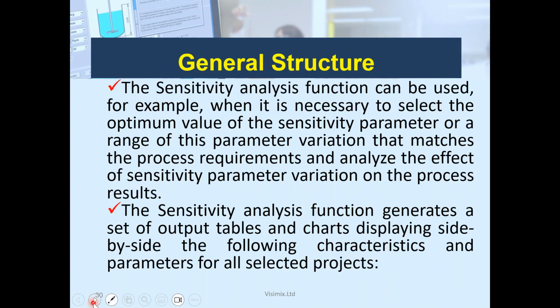So once we are doing all this range from the minimum and maximum, we will see that the results are giving me all. It is not only the drop size. It's giving me the solid distribution, but all the other parameters regarding solid liquid. So the solid distribution, axial, radial, the frequency of collision, the complete or incomplete suspension, and below that, we can find the power per volume, the mixing time, all the main important parameters that are connected to the solid liquid phenomena that are very frequent in the industry.